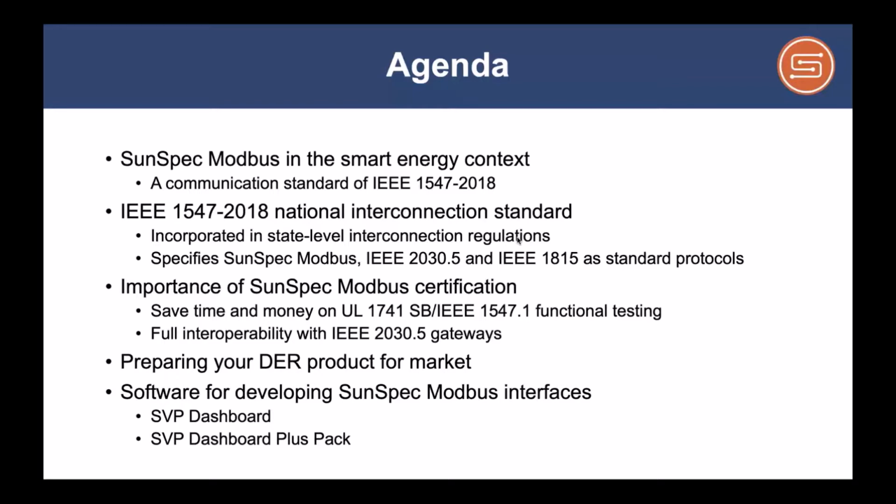Second benefit, of course, of SunSpec Modbus certification is that it guarantees full interoperability with these other data communication standards used by IEEE 1547, and most notably IEEE 2030.5.